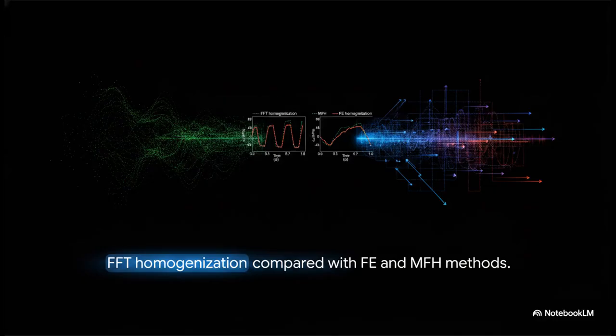Now, this graph perfectly illustrates the contrast we're dealing with. It compares 3 different ways of simulating how that woven geometry handles stress. Check out the dotted green line. That's mean field homogenization, or MFH. It uses the two-step mathematical averaging procedure. It's lightning fast, taking just 30 seconds to run. But as you can plainly see, it deviates a lot from reality under complex cyclic loads. So that's our low-fidelity data.